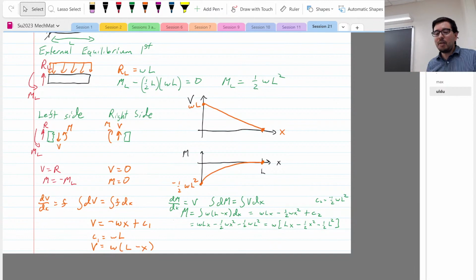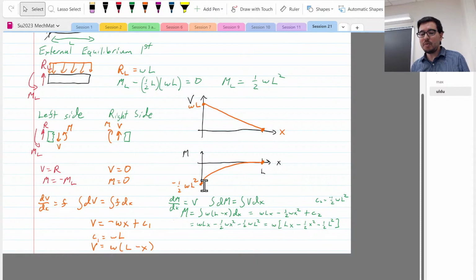Now, there are a couple things to point out. I think you're getting at, Carlos. If the question is, where is the maximum bending stress? I don't have to do a whole lot. Just like you said, it's right here. I solved it way back over here when I figured out the internal moment. I don't have to go through everything. If you want to know where's the maximum transverse shear stress, again, left side.